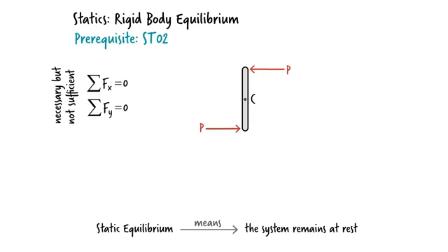Let's show the line of action of the force. Visualize a straight line connecting the line of action of the force to point C. Obviously, we can draw an infinite number of such lines. Nevertheless, we are interested in the shortest line, the line that is perpendicular to the line of action of the force. Let's refer to the length of this line as r.